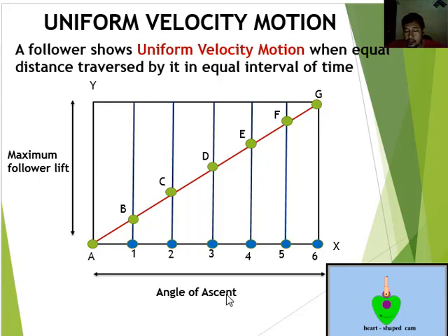This represents the time, or it may represent the cam completing one revolution. It may represent the angular displacement, velocity or acceleration of the follower. This is the maximum lift, and this is the angle of action, for the angular movement, or theta.